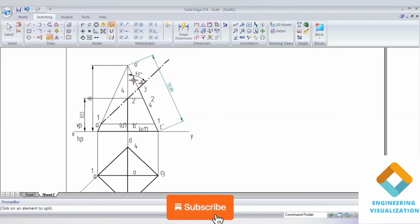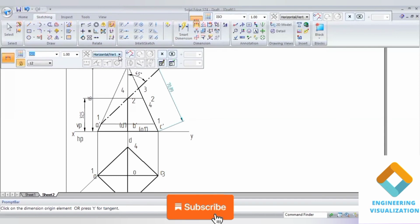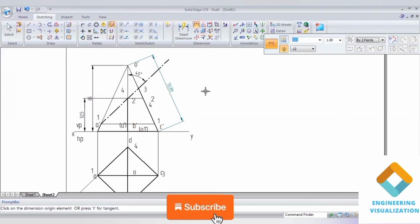For this I'll be using the split command to get the exact length here. In the distance between command there is an option: distance between two points. If you select it, you are able to measure the dimension. This is an important step, guys. You can make use of this particular command. Select these two points. This will give the slanted line.